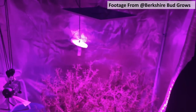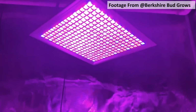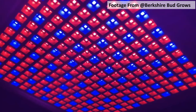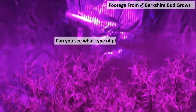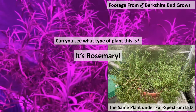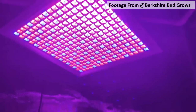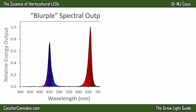The engineers who designed the early generations of horticultural LED fixtures recognized the need to activate both photosystems, so they included red and blue monochromatic diodes. This produced a garish red and blue light that growers call Blurple. It worked reasonably well for driving photosynthesis, but it was visually awful and makes it difficult to see the plants clearly. Blurple light has only red and blue light. The spectral output curve looks like this.